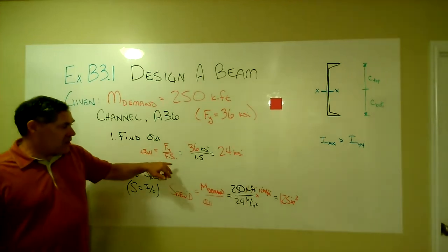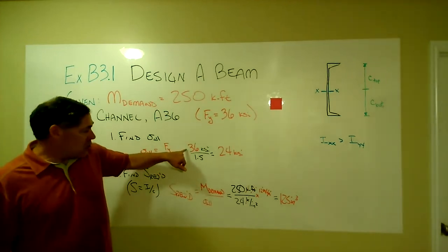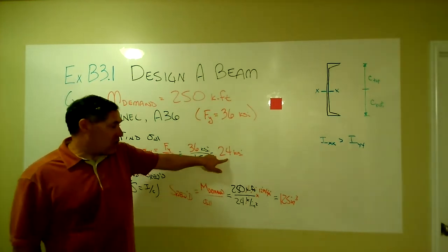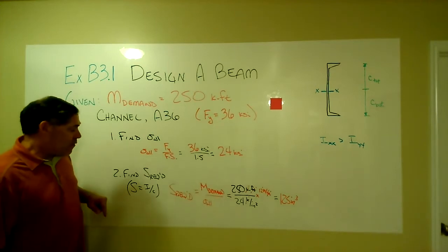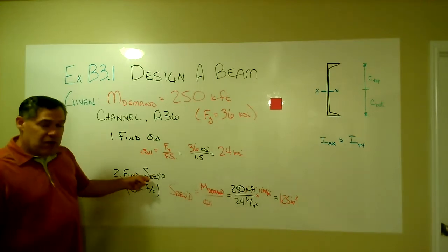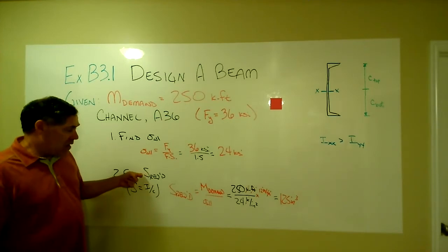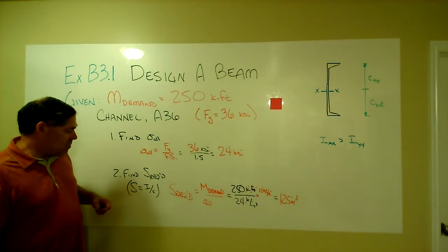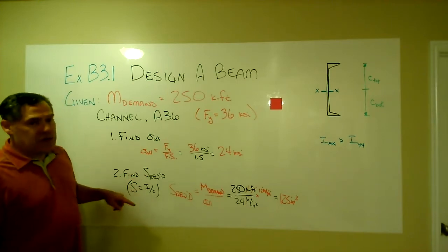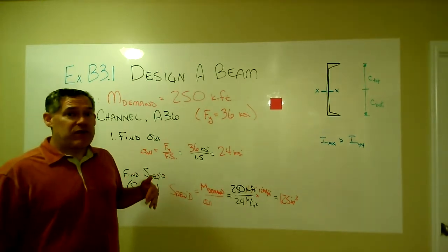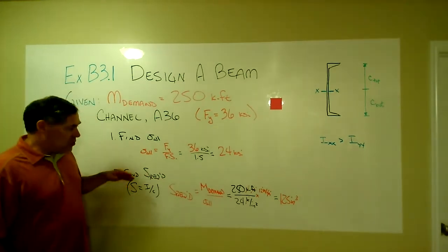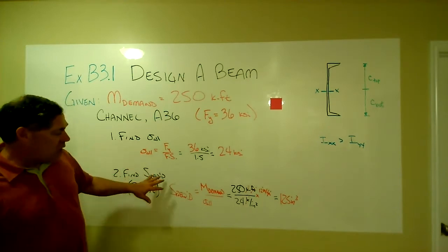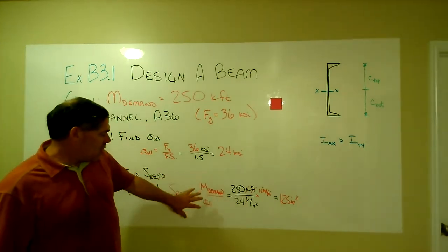All right, so remember last time we went and found the allowable stress. That was our yield stress divided by the factor of safety. Because the yield stress has changed, then our allowable stress has also changed, and we're down to 24 KSI for our allowable. We find a geometric property that's required so that we have sufficient strength by looking at that elastic section modulus that's required. Remember that all came from that S is equal to I over C, sigma max equals MC over I or M over S, set the allowable stress equal to the maximum applied stress, and that's how we derive this particular expression.